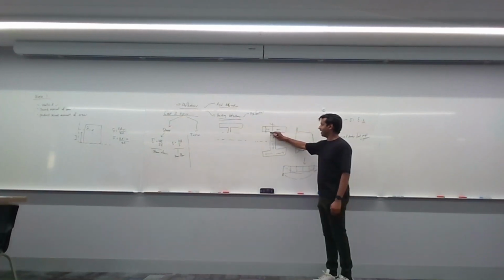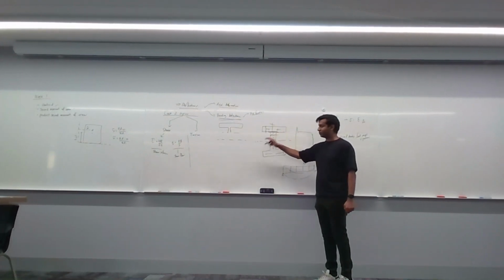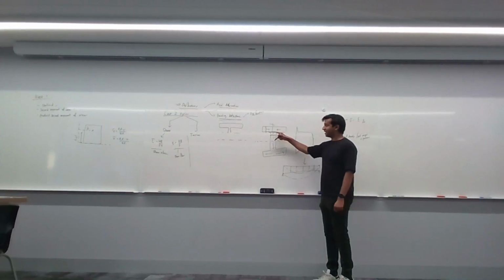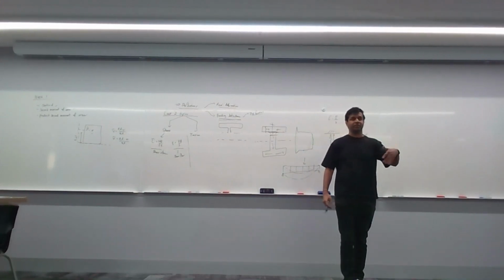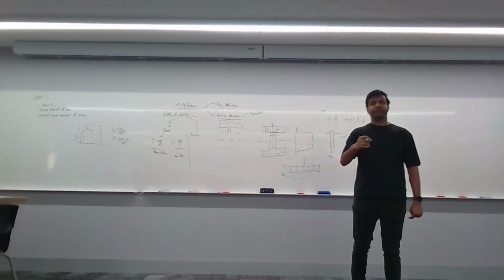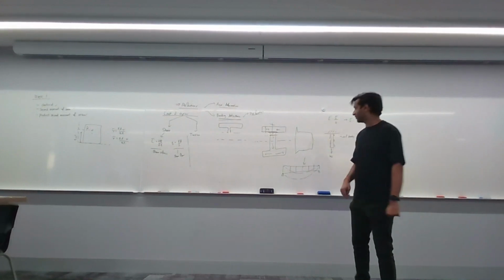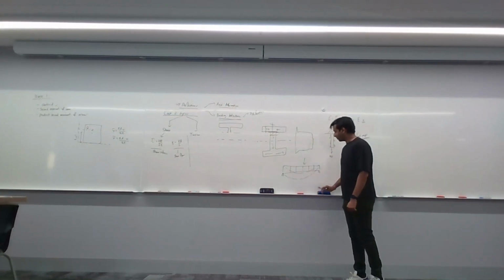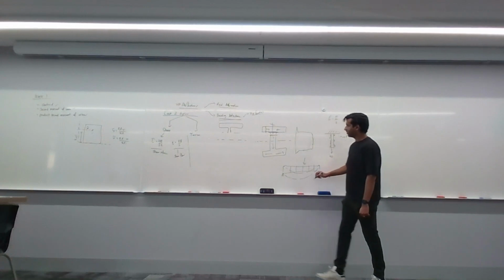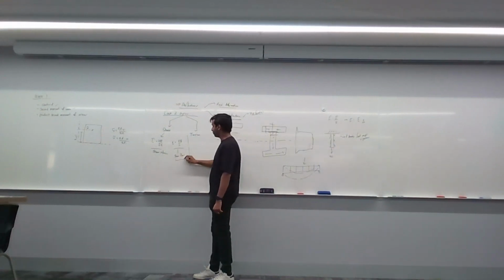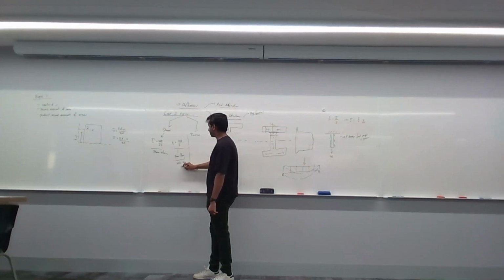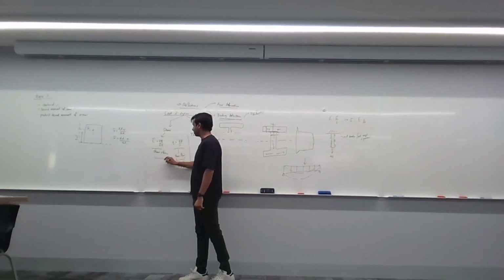Let's say I can calculate the shear flow here, just use VQ over I. But that gives me, in newtons per millimeter or whatever the unit is, the shear flow into the page. So remember, if you have a beam here, I'll just write it down here. Shear flow is in the direction into the page. Shear stress is in the direction across the page.